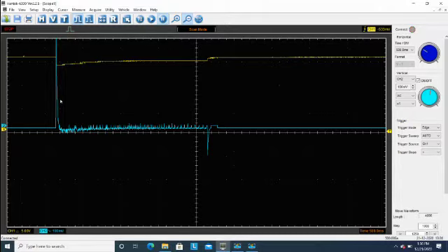Notice that our yellow line, our voltage, changes inversely to our current flow. Well, why is that happening? As current is flowing out of our battery, it is causing that drop in voltage to take place. So when our current spikes, we see a very high drop in voltage. As that counter-electric motor force starts to develop, and as that resistance from the copper heating up starts to increase, the current flow decreases, and we see the voltage start to increase back up to where it levels out.